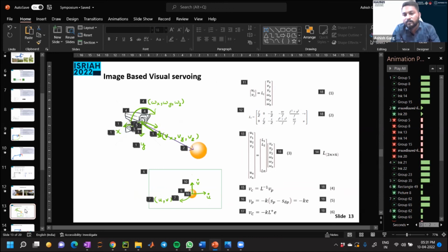We are in the process of implementing this, and with time we'll make modifications to get better results. In the initial stages we are using the traditional methods, which directly use the proportional controller, and we are adding things to the traditional method. Okay, my practical experience is that if you use only proportional gain, there are some oscillations, so in future you can certainly look into it.